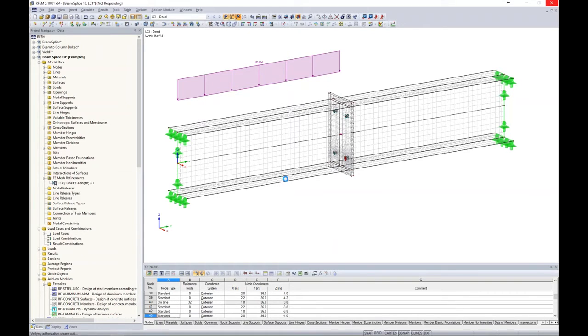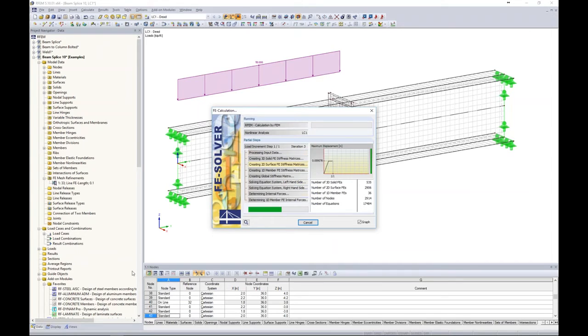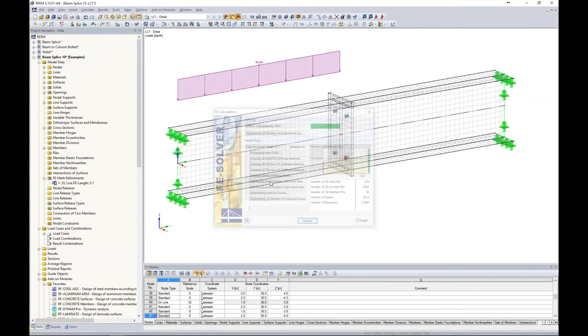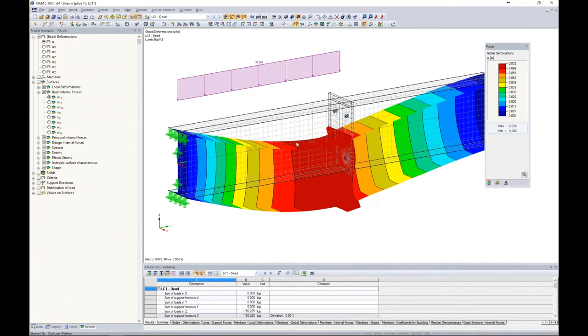And keep in mind too, we can see down here what the program's doing. It said verifying authorization, so it was checking my license. It is a nonlinear analysis program, so the contact solid is something that's going to increase our solution time as well, and that's just because of that different behavior that we defined between the two plates. So that analysis is ran, and we are automatically brought into our results tab here, which is available within our project navigator that I mentioned at the beginning of the webinar.